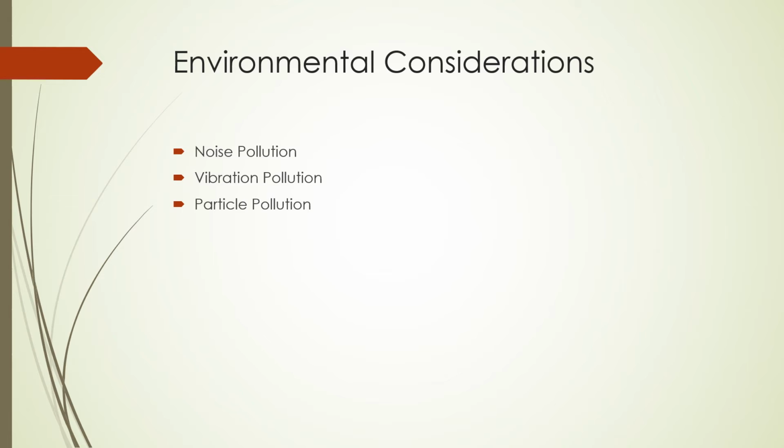Furthermore, within project phases, certain environmental considerations are needed which can ultimately affect how the design and construction of the overall project are run. In accordance with multiple guidelines, these can be listed as noise pollution, which can negatively affect both humans and surrounding fauna, vibration pollution, which can negatively affect the structural integrity of surrounding buildings, and lastly, particle pollution, which is highly evident in excavation work and can negatively affect the respiratory system of humans and animals, and can be eliminated through the use of watering down the dirt during excavation.